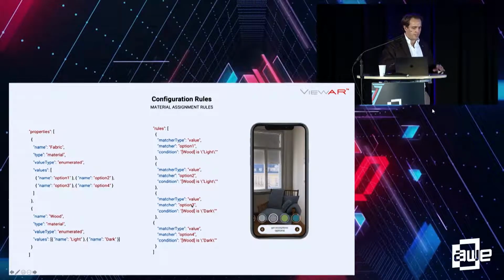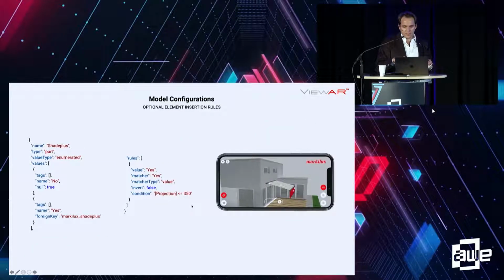And it's way more complex, and the abilities are way richer than I just showed. But this is the base principle. And for the case of the awnings that I've previously shown in the video, we have so-called parametric items. So we have created an algorithm that lets us mark and define parts of geometries that should be stretched and parts that shouldn't be stretched.